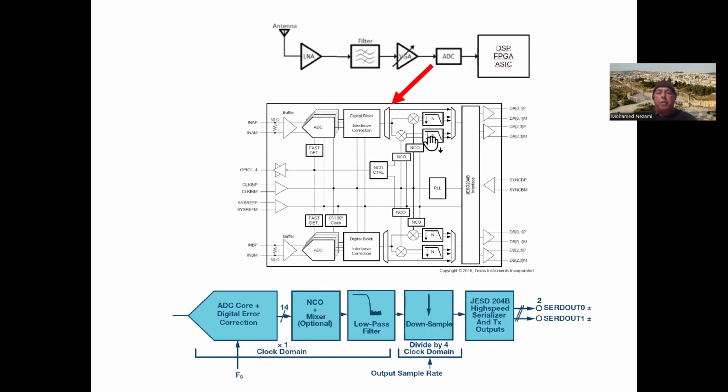And so we have the frequency translation here. We have a numerically controlled oscillator, NCOs, here to drive and rotate the frequency. And then we have the decimator filtering, which reduces the bit rate so that when we go to the serial interface, the JESD204B or C, we have a much lower, more manageable speed on these buses.